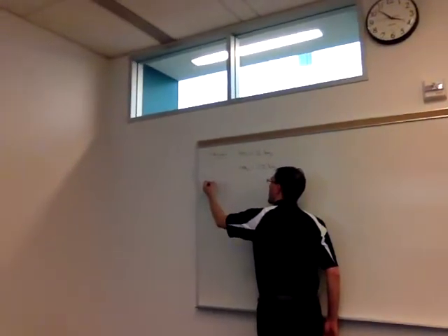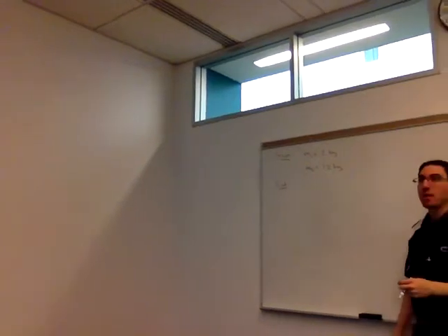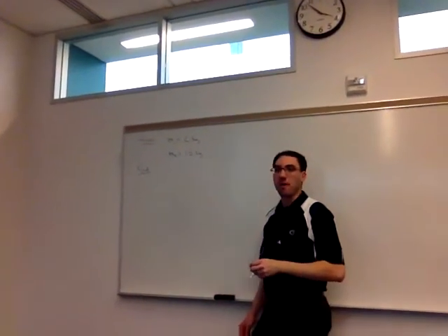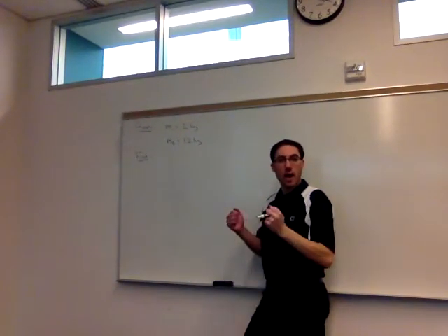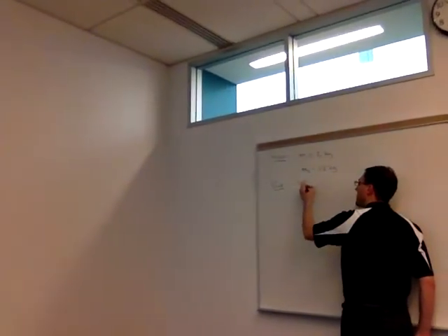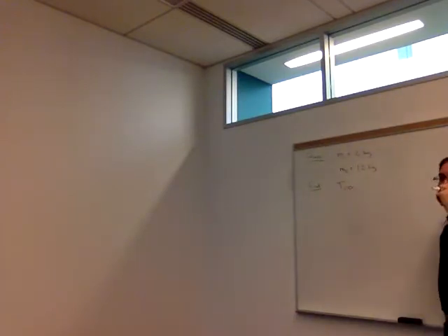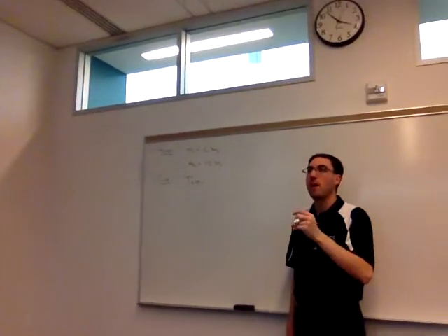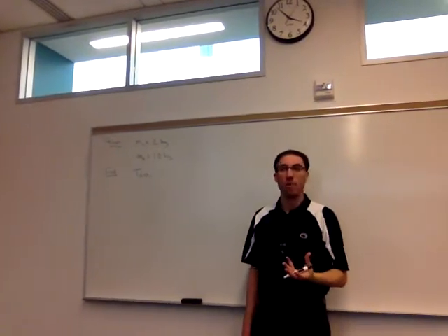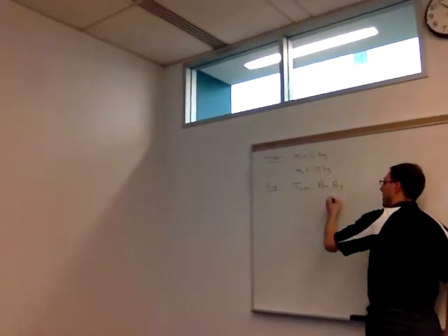So we're looking for 3 things here. We want to know the force in the muscle, which we're modeling as a rope, which is appropriate because muscles can only pull on things. Muscles can't push on things. So I'm going to call that tension CD. And we want, in component form, what the forces on the elbow joint are. So BX and BY, since we're going to model it as a pin joint.